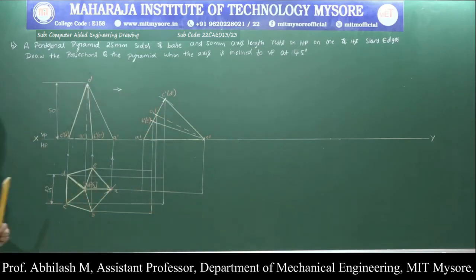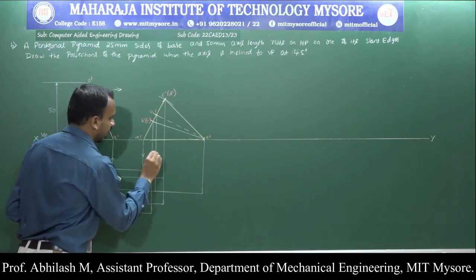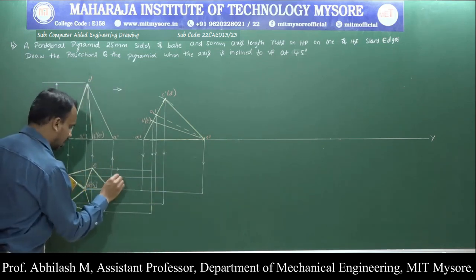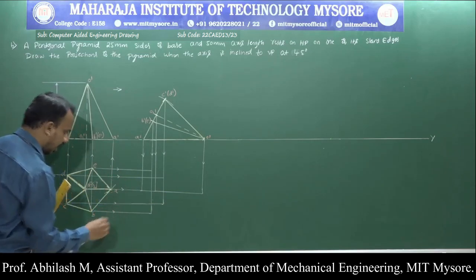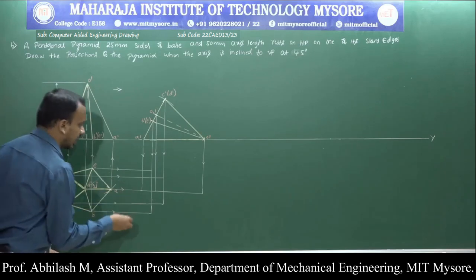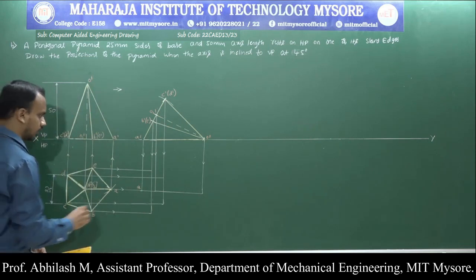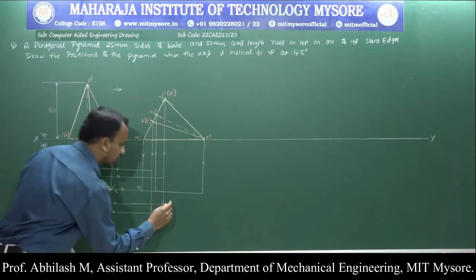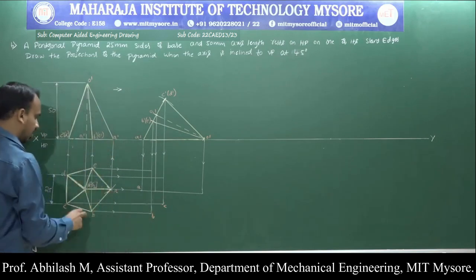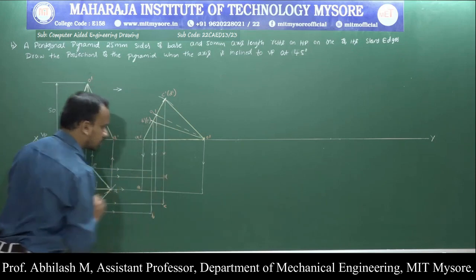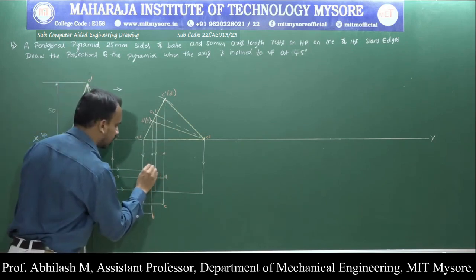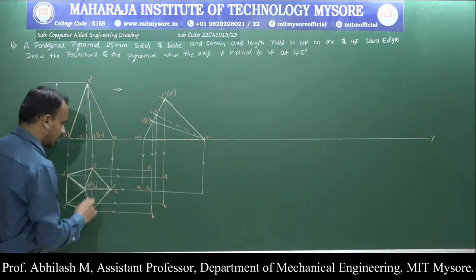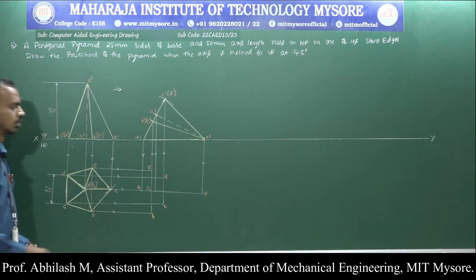We have successfully drawn all the projection lines from the corners of A, B dash of E dash, O1 dash, C dash of D dash and the O dash. Similarly from the corners of E, D, A, C and B. Let us identify the points. So A and A dash, this point will become my A. From B, C to C dash, the point of C. Similarly from D to D dash. Similarly from the point of E to the point of E. O1 dash, that is indicated as O1. Similarly the O dash, there it is O.